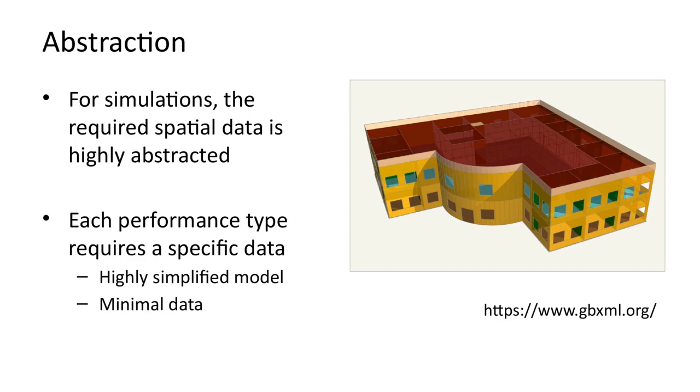The detailed form and structure of the building is not represented, as it is not relevant for a thermal simulation. The thickness of surfaces such as walls and slabs are also not modeled. Instead, building surfaces are defined using polygons. The material properties are defined as attributes attached to the geometric entities. The image shows such a model.